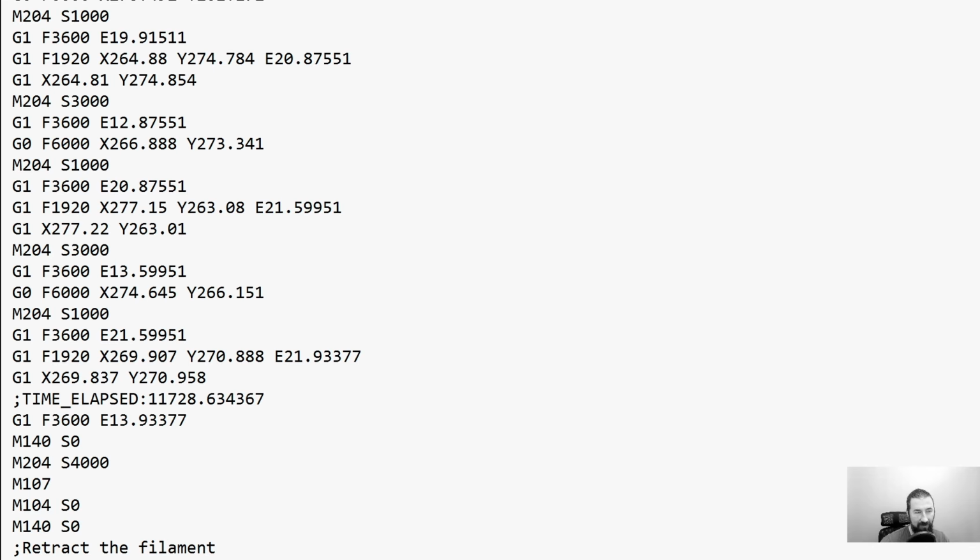So in terms of machine compatibility, most of G-code is 100% compatible with any machine, if you take care of your coordinate system, so you need to be in the coordinate system of your printer. This means knowing the zero point of your machine, knowing the print area, and using these pre and post commands in the right way. This may vary from machine to machine, but the rest is usually the same.